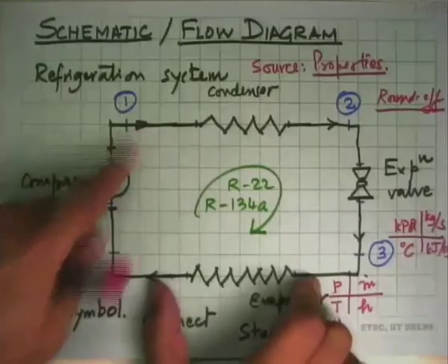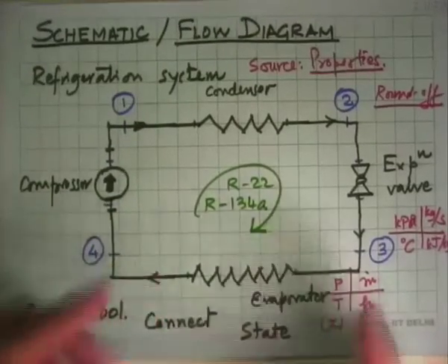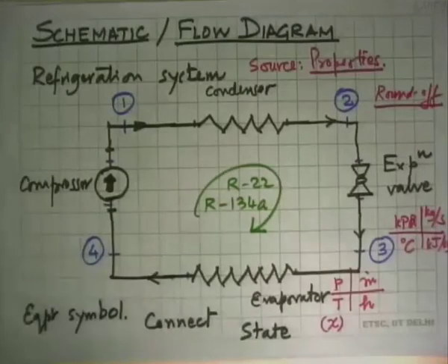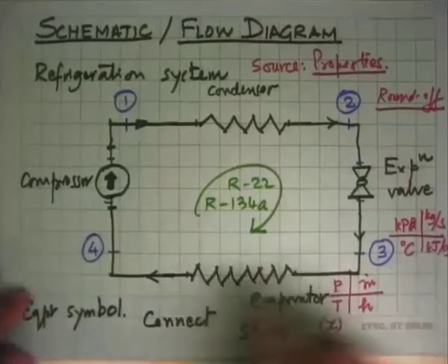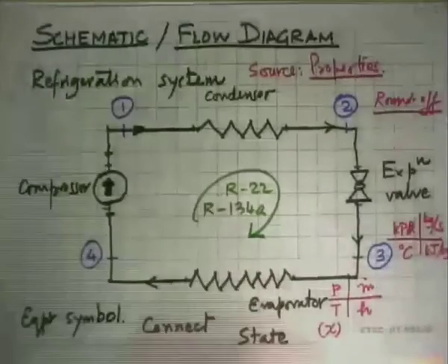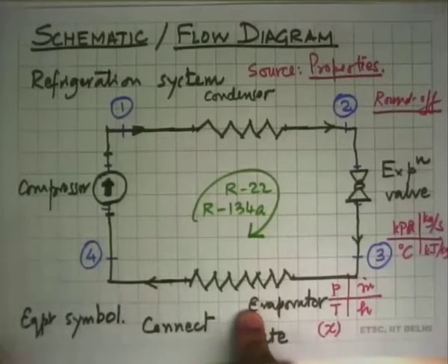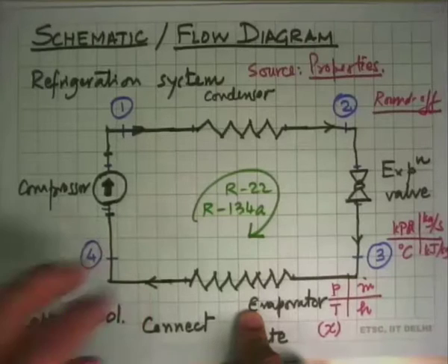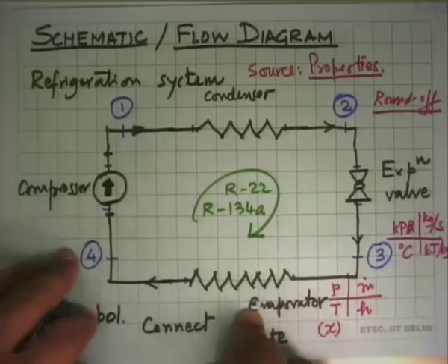The evaporator, for instance, we will know that we need to go from this state to this state and so much mass flow rate is there. Then we can calculate and see how many tubes are required, how many fins are to be put, what is the physical shape and size of it, what should be the pressure for which the tube should be designed so they don't rupture. All those designs follow this fundamental information. So in the design of all of this, this particular type of a system is hugely important, and it's important we get it right.